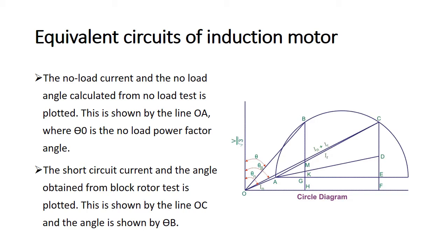The no-load current and the no-load angle are calculated from the no-load tests of an induction motor and are plotted as shown on this side by this diagram.